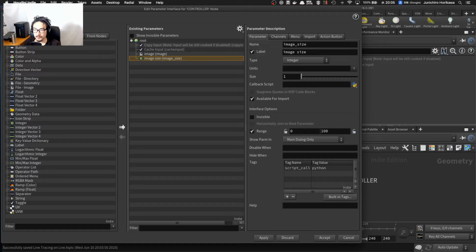And in order to control the flipping pattern, flipping of the diagonal lines, so in some part I want to flip the diagonal line which goes from left bottom to right top, to the right bottom to the left top diagonal line. So in order to change that, I am going to create some boundary geometry like a sphere or metaball on top of the image. Where the image is covered by those spheres, I want to flip the diagonal lines 180 degrees. So in order to create a sphere, I'm going to set a number of spheres or metaballs, saying pdnum indicates the number of balls. And let's also create a float parameter called ball size to determine each ball size.